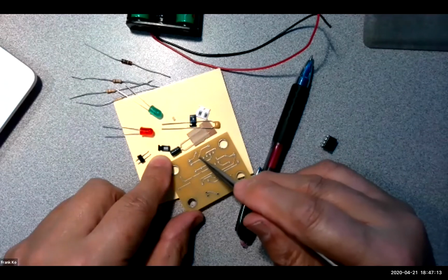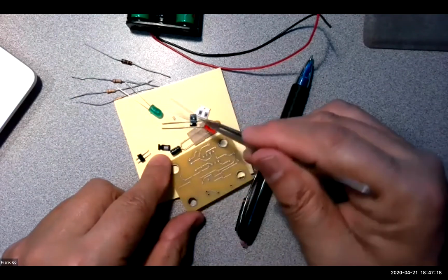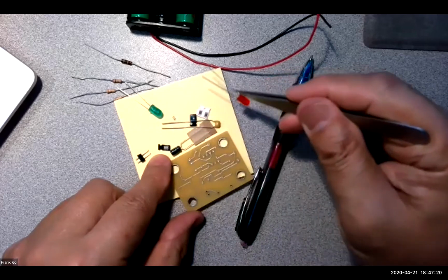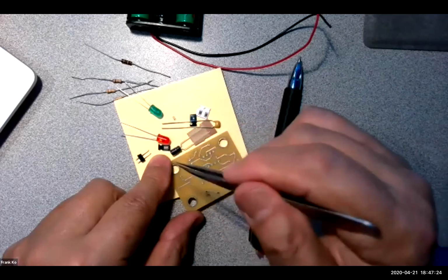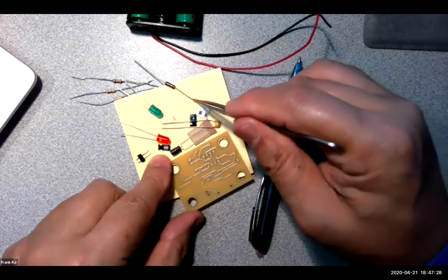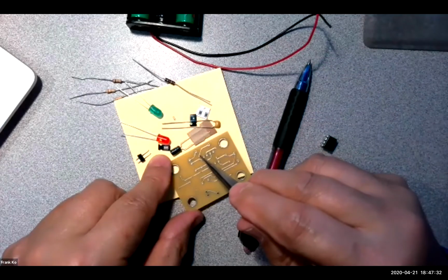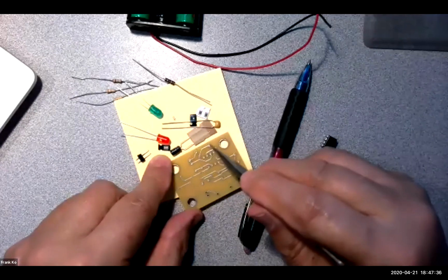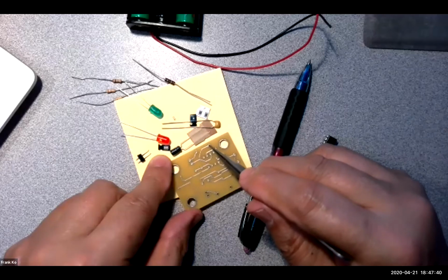So whatever device was here, you simply use the leftover wire, and you have leftover wire for each one of these, a lot of leftover wire. After you solder the LED on the board and after you solder resistors on the board, you have a lot of leftover wire. You just simply use one of those leftover wires and you solder one end of the wire to this component at this point, and then the other end of the wire to the wire that's sticking up out of this hole that has nothing to solder to.